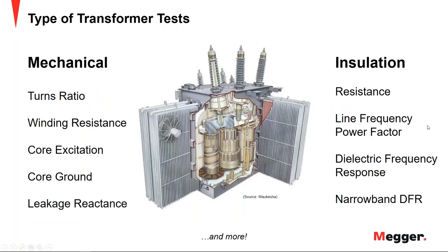So certainly not all transformers can be tested for all different tests. For instance, on dry type transformers, sometimes it is not recommended to do power factor testing because the numbers can be unusually high. The test that is recommended for dry type transformers more so is the tip up test.